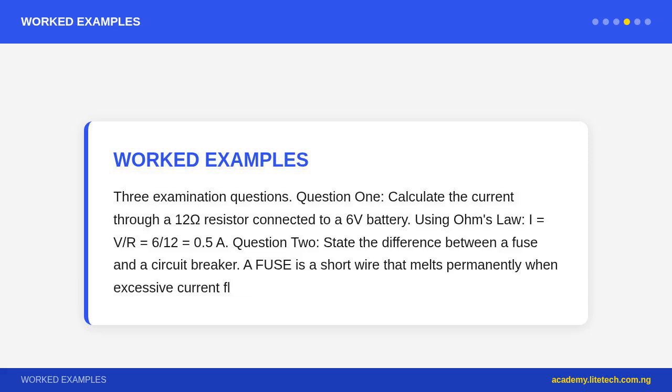Correct wire color codes, Nigerian/BECE standard: live equals brown (older: red), neutral equals blue (older: black), earth equals green/yellow. Always respect wire color coding.